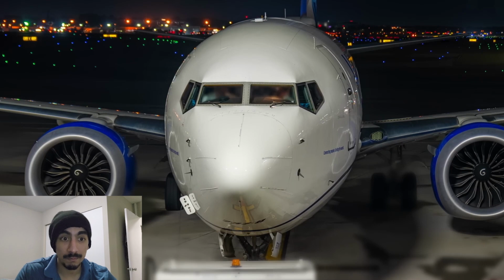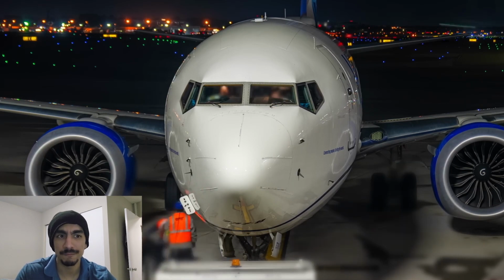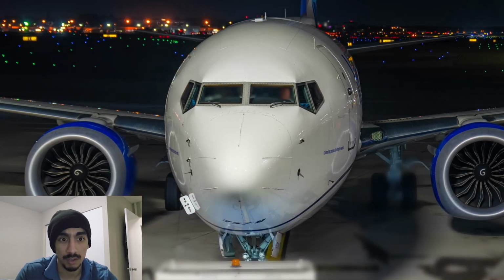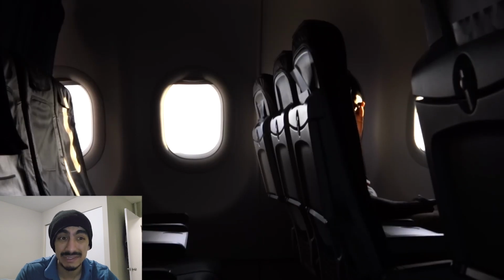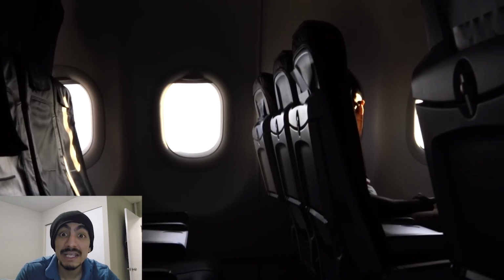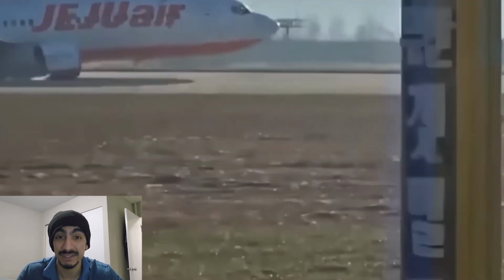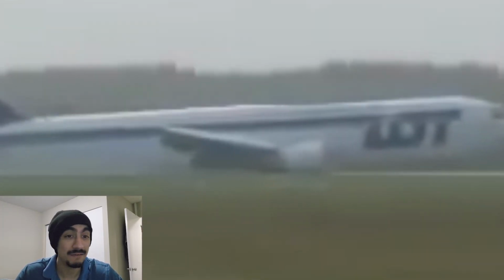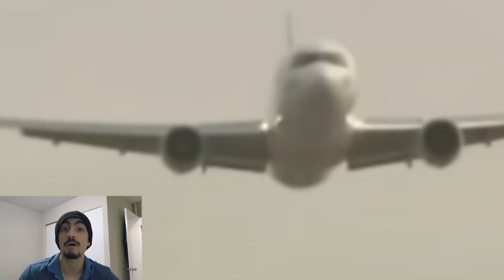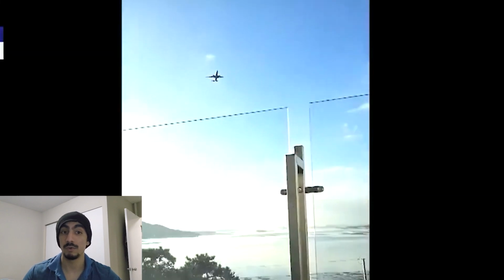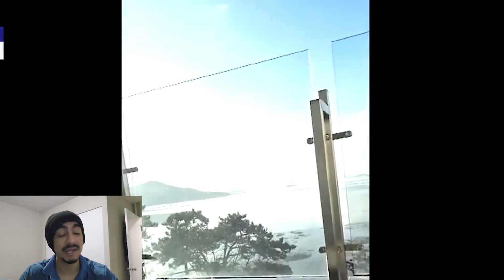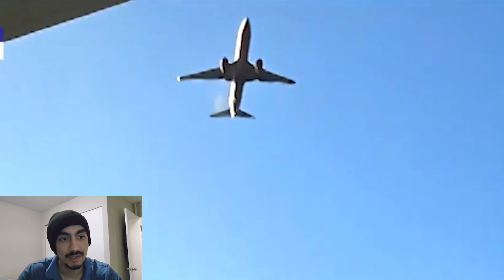So the fan blades themselves are made of titanium and nickel-based superalloys, which are very, very strong. But at takeoff and landing speeds, the kinetic energy of even a single bird flying into the turbine, into the engine, can be massive, okay? And you have these blades spinning at thousands of RPM. Suddenly introducing a bird is like throwing a chunk of metal into a high-speed fan. It can bend or fracture the blades, it can cause vibrations.